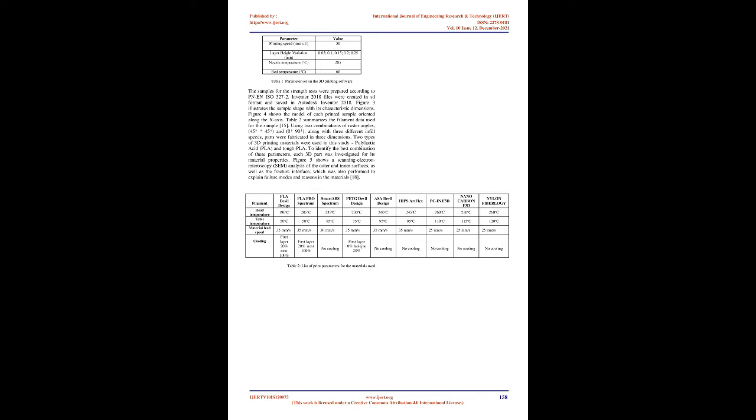Despite its high tensile strength, 75 MPa, nanocarbon has one of the smallest moduli of elasticity, 0.62 GPa. In PC, polycarbonate, similar to nanocarbon, the tensile strength is 64 MPa, and the modulus of elasticity is 0.52 GPa, the smallest of the tested materials. Both materials are suitable for building high-strength machine parts.